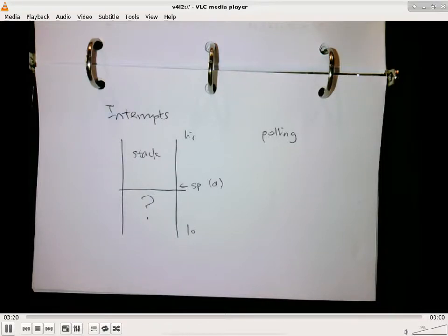On the keyboard itself, it has its own controller, which is a very tiny processor. It continuously scans and goes like, okay, I'm putting a voltage on the first row of all the keys, and then it senses the columns, which one is detecting the high voltage. That way it knows this particular key and that particular key are pressed.